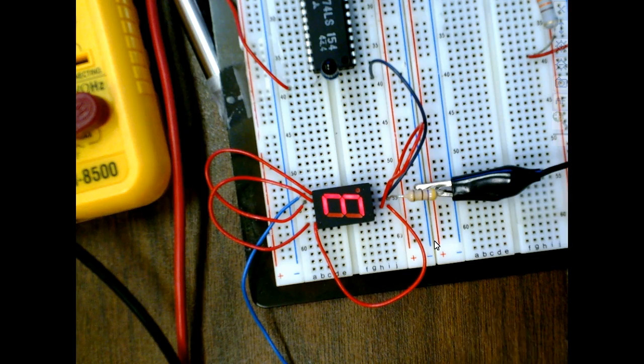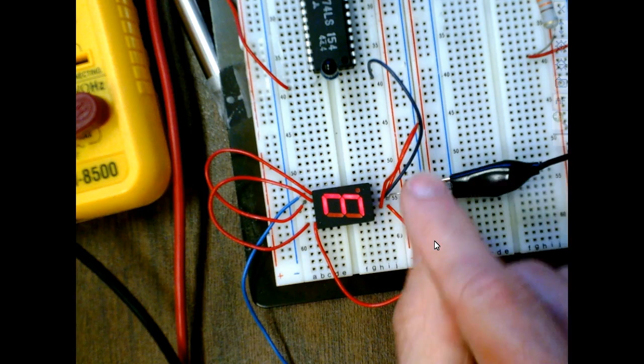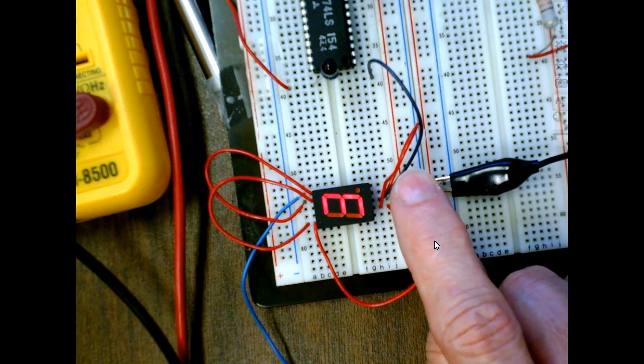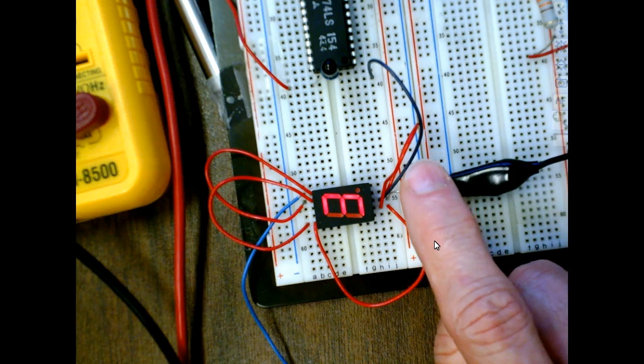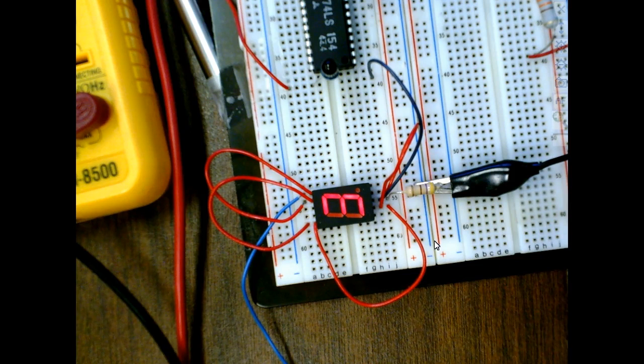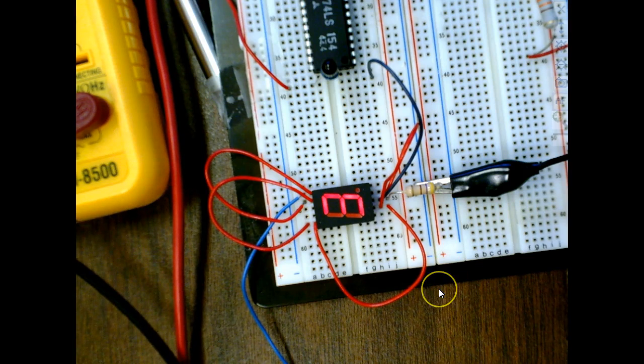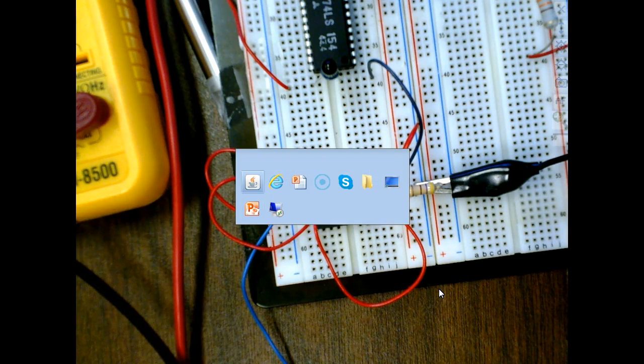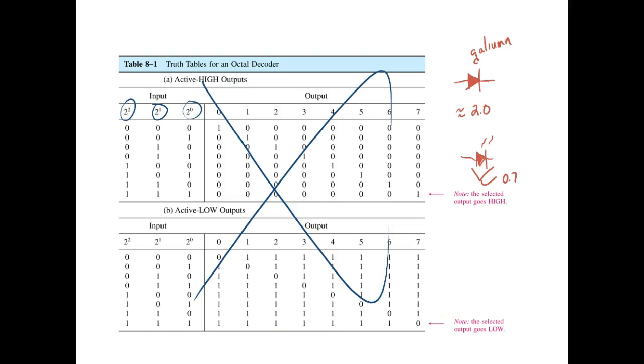By the way, what we usually do is we put one resistor per LED. Now you think about it, these guys here roughly drop about 2 volts. We'll look this up, but usually the voltage drop, if we don't know it, we assume to be around 2 volts, but actually it varies with color. And normally we run these at about 15 milliamps.